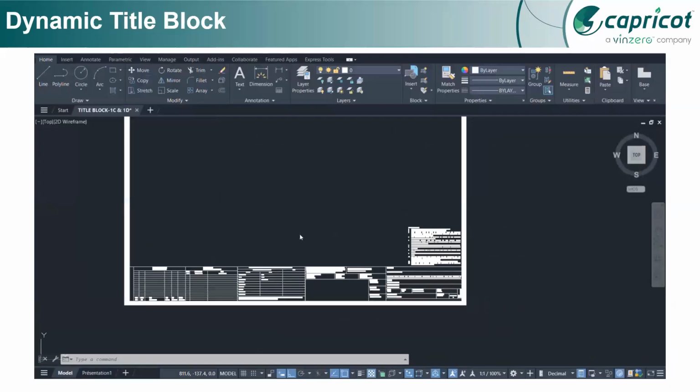I have a title block. Now in the title block also have a lot of options. So in the title block, you can convert your whole size of blocks, right, into your A0, A1, A2, A3, right? The same kind of blocks you are going to convert and make into your dynamic block, from where you can change with a single click and change all its dimensions with a dynamic distance or dynamic increment or dynamic listed values. Okay, so that is also one of our stuff.